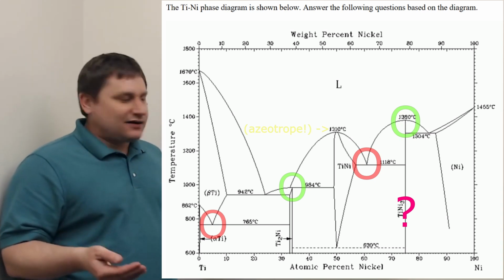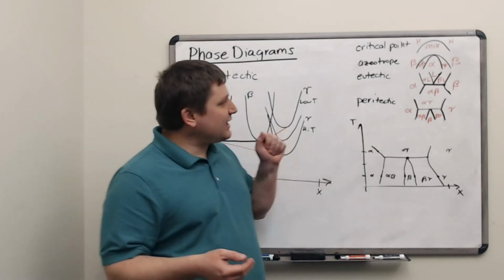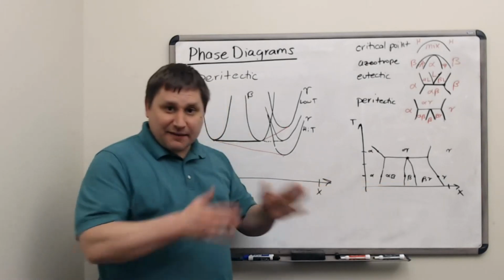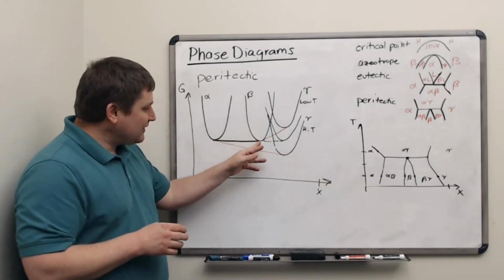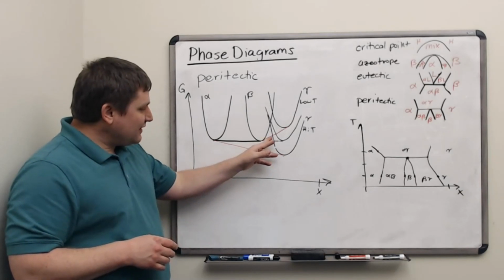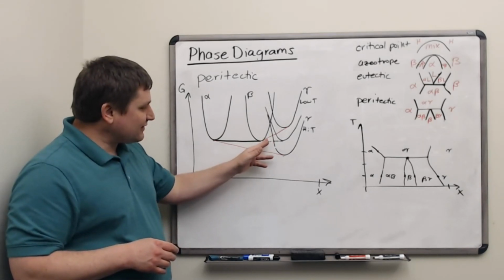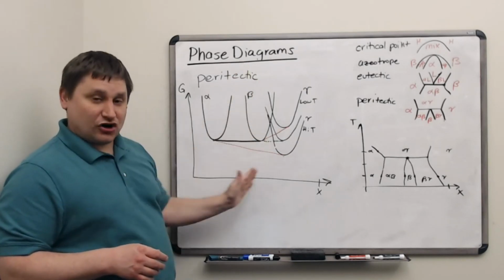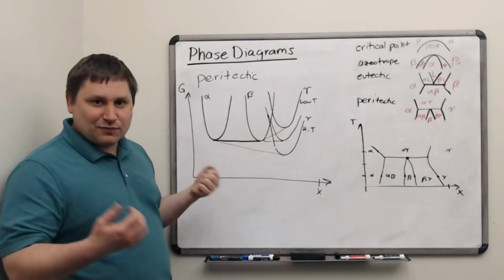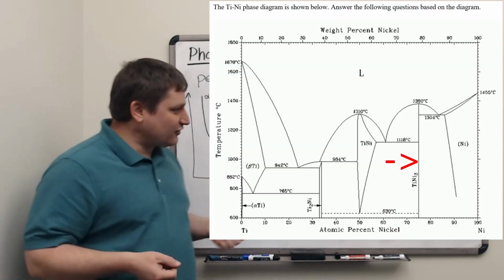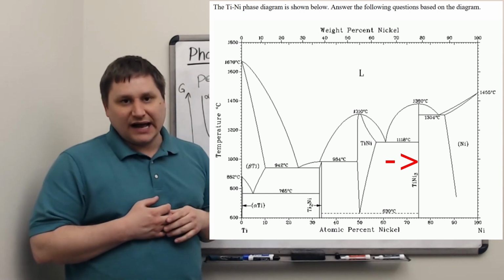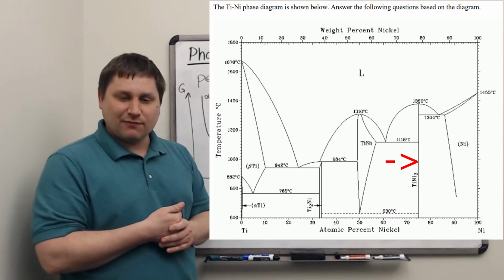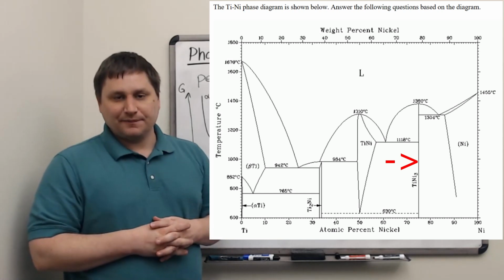Well, in reality, when you have these peritectic and eutectic points, the region of beta, like here, can be extremely narrow. Remember, the region of beta was based off of the region between these two tangents touching here, right? And if this beta free energy curve is really sharply pointed, then that region can be super duper narrow. And so it usually is just drawn as a straight vertical line on the diagrams. Not really possible to nail that composition perfectly to get that crystal to show up.